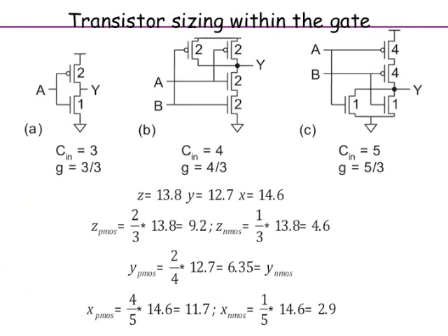And not only that, maybe ordering, a lot of optimization it does. Because when you synthesize, you have to give a certain delay constraint. You have to say synthesize to meet a certain delay. So there the optimization problem is a little different. There what we are saying is, you meet the delay, but you minimize power, or you minimize area. Area and power are related mostly, so you want to minimize area or power while you meet a certain delay constraint. So that is a more general optimization problem.